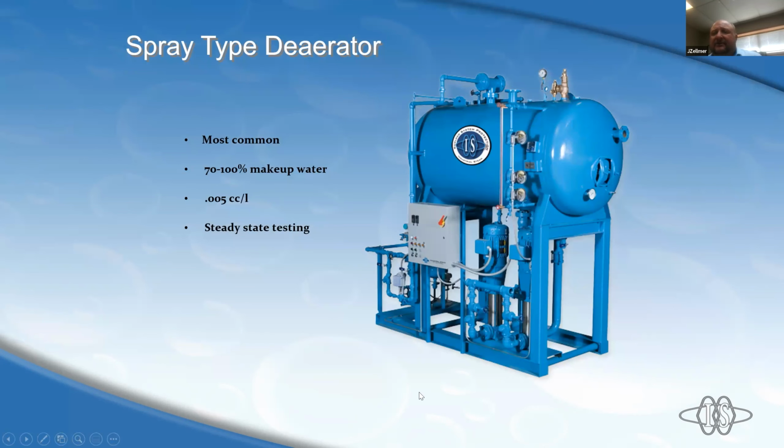Here's kind of a general layout of what the deaerator looks like. As we said, it needs steady state conditions, and so we recommend using it in a 70 to 100% makeup water condition.